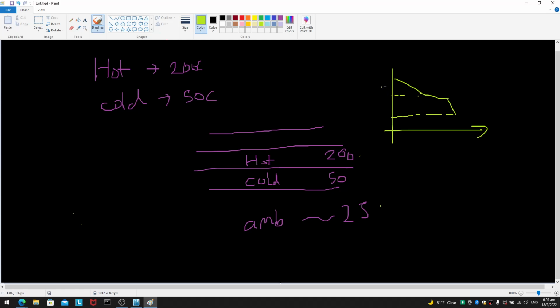You have the shell side, then the tube side will be at the top. So basically, if you want to prevent this heat loss, parasitic heat loss, you enclose the fluid with the greatest temperature difference with the environment. You put it in the tube. Then the fluid with less temperature difference compared to the environment, you put it in the shell.